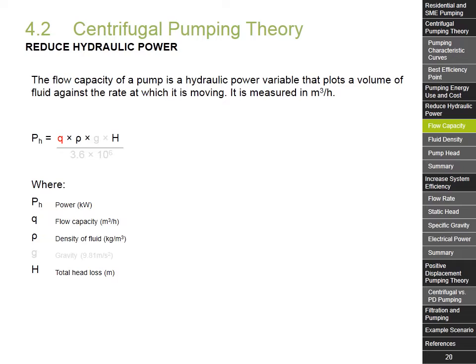Flow rate, or capacity, is rarely calculated in assessments. Instead, if that information is not available in a manual or on a data tag, the rate is measured from a tap, hose, or similar. To do this, you can use specialized flow rate equipment or simply measure the time which it takes to fill a container of a particular volume.